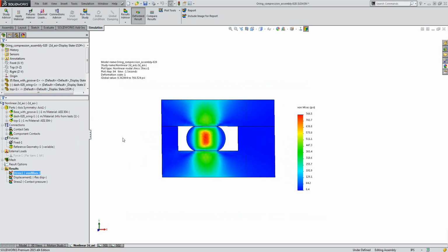Now, let's just say, for example purposes, this hole was significantly smaller. So instead of just touching the top and bottom, the O-ring is going to start hitting the side walls as well. So now the boundary is going to play a big role in how this O-ring is going to close these two plates.